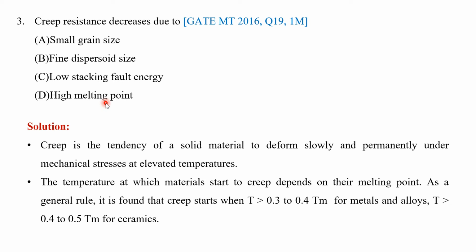When we are discussing creep, it is necessary to define homologous temperature. Usually, when you are reading lectures on creep, you'll come across this term. What is high temperature for one material need not be high temperature for another material, right? For mercury, room temperature itself is high enough; it is a liquid state. But for something like steel or aluminium, it is not high enough at room temperature. Therefore, different materials will have different high temperatures, and it is necessary to equalize all of this. That is why we usually plot creep in a case where T by Tm is measured.